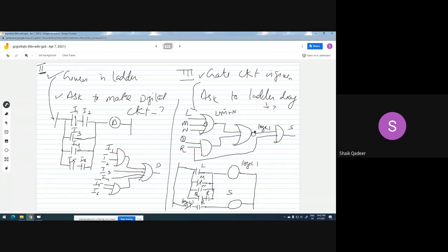There can be many different ways, but in ladder realization, logic inversion is quite simple. So what I'm doing here is realizing OR logic up to here, and the output of OR is simply inverted in the second rung along with this AND connection.